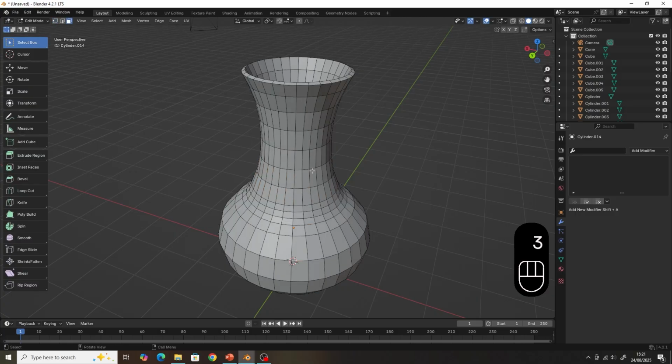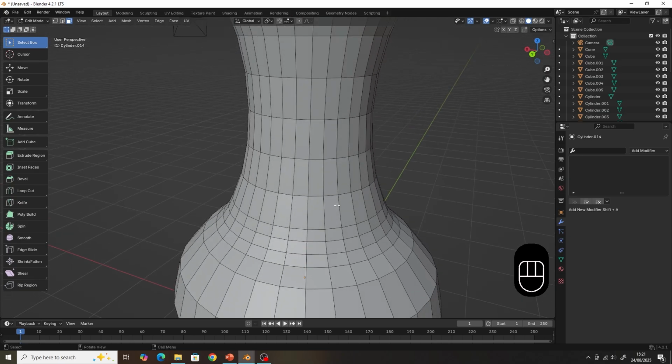But with the faces, it can be a bit difficult to say, oh, I just want this loop, but you accidentally get the vertical line. So to make sure that you get this right, press and hold Alt and you go towards the closest edge where you want that loop to go. If you want to go vertically, you select the horizontal edges, or you select the vertical edges to create that loop.